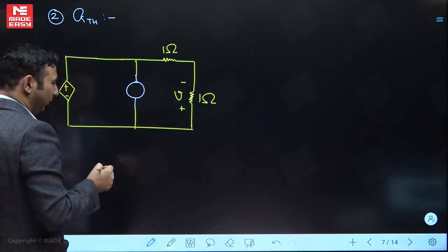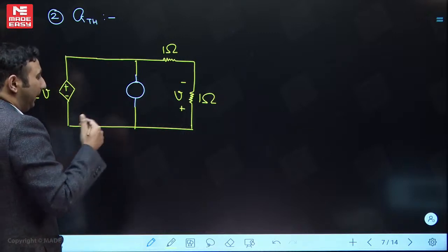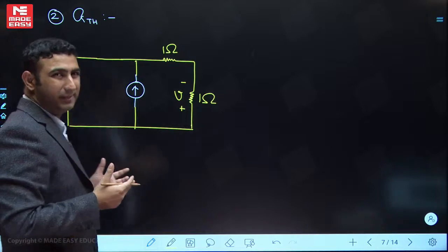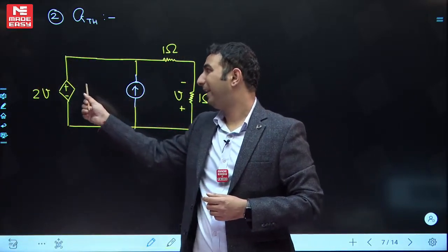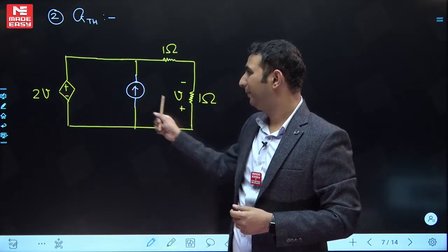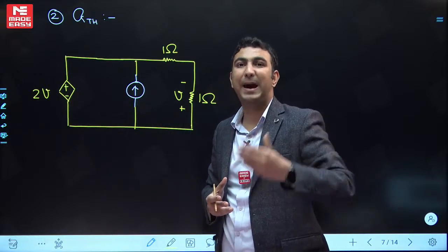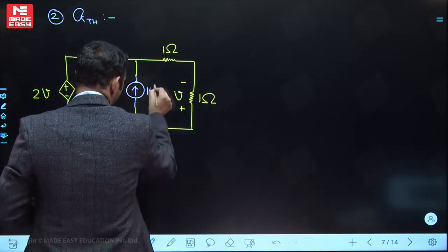Let's connect a voltage source or a current source, whatever you want, but I have to connect a current source, because we have dealt with this concept in great detail. If I connect a voltage source, then I'll be defining the value of the dependent source, which we shouldn't be doing, because this variable should be defining its own value. So we never connect an independent voltage source in parallel with the dependent voltage source. So 1 ampere I'm going to connect over here.